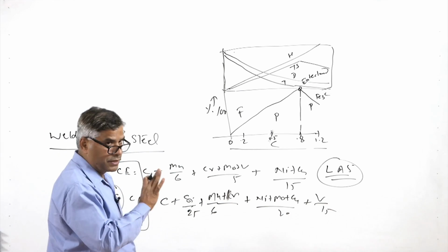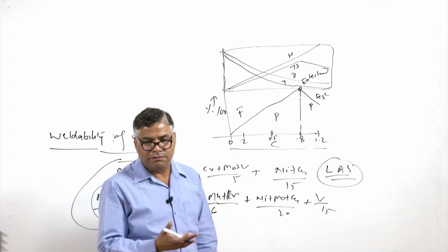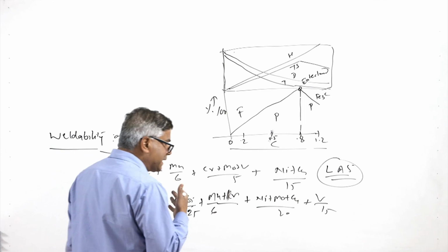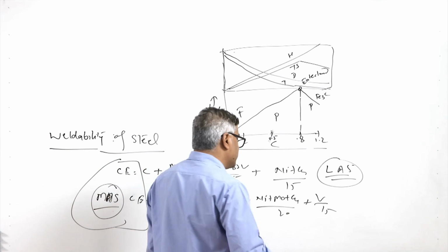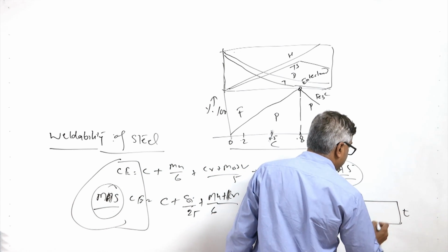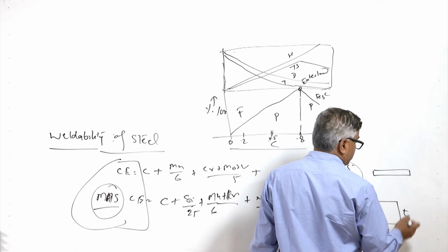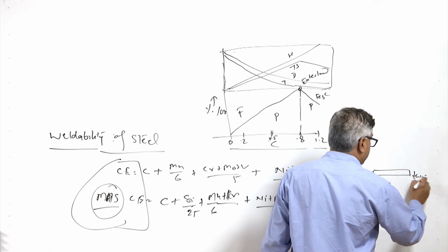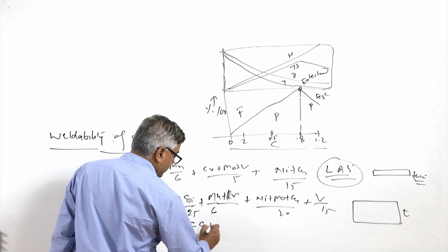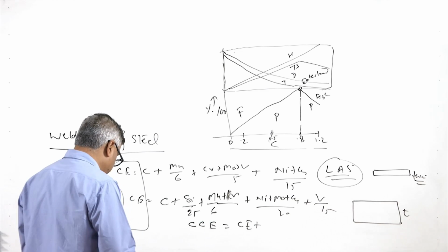There is another equation which also considers the thickness of the plate, because it determines the area available for transferring the heat. That will also affect the extent up to which hardening will take place. The greater the thickness, the easier the hardening of the metal. Under identical conditions, a thicker plate will get hardened much more easily as compared to a thin sheet. So, to consider the thickness aspect, the compensated carbon equivalent is calculated, which is obtained from the carbon equivalent plus